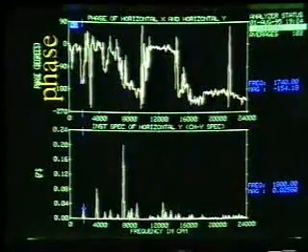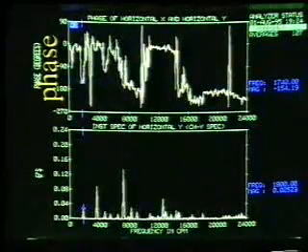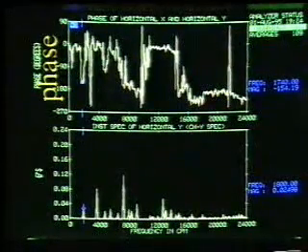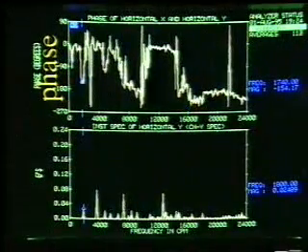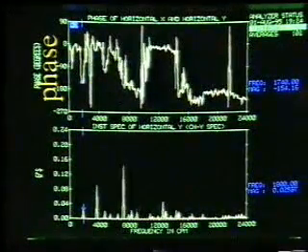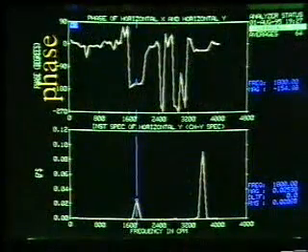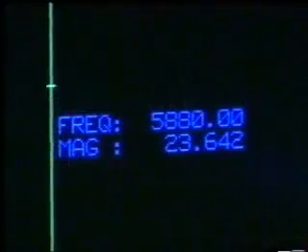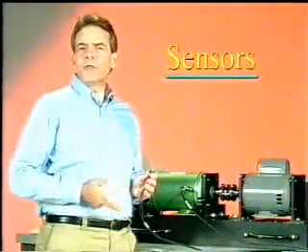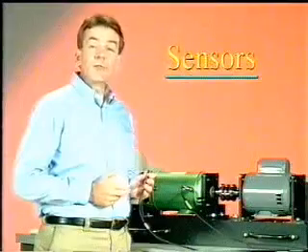Because this capability is here, there is also the ability to display the phase relationship for every frequency in a phase spectrum. This spectrum has frequency as the x-axis, but has phase in degrees as the y-axis. Now we move the cursor to a particular frequency on the reference spectrum and read from the phase spectrum the corresponding phase angle. In order to use this cross-channel phase effectively, certain setup considerations must be made.